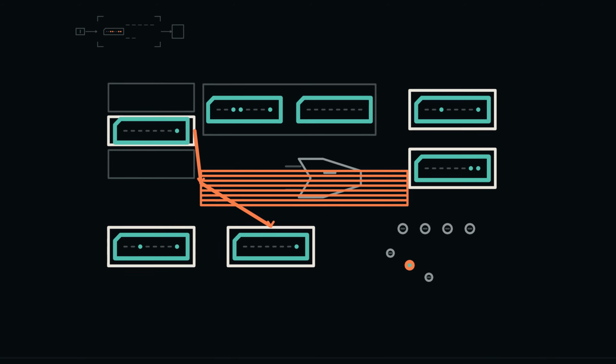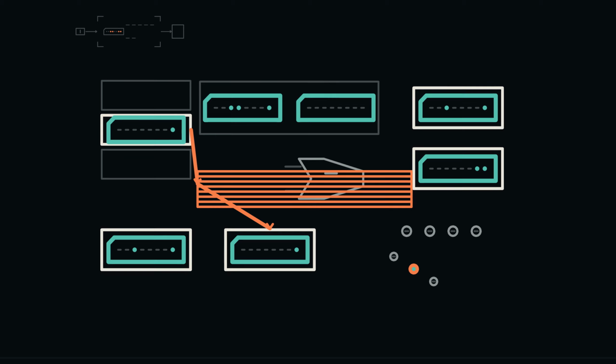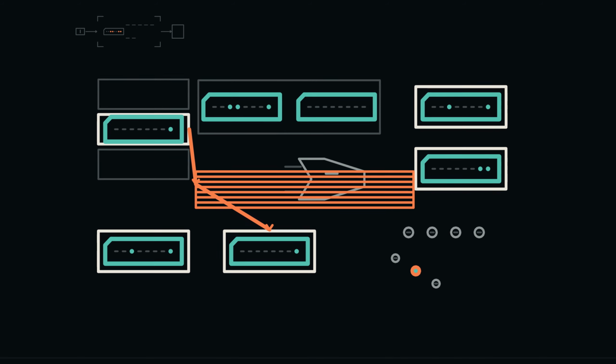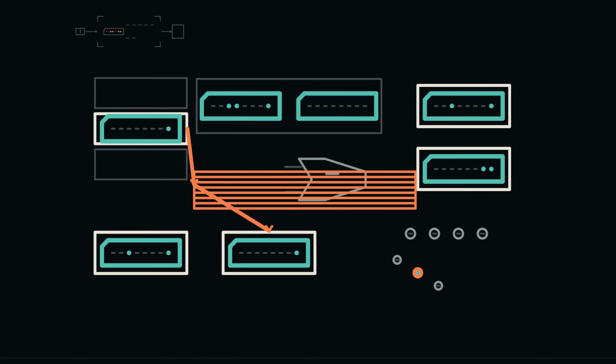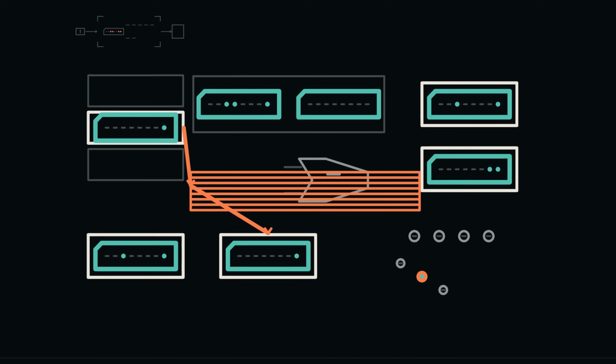The second byte begins with the same 3-action memory pattern. In fetch 1 address, which value must reach MAR? PC now holds 21, so MAR captures 21. In fetch 1 read, memory at 21 provides hexadecimal 01 and MDR captures it.